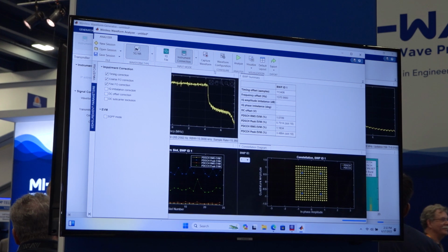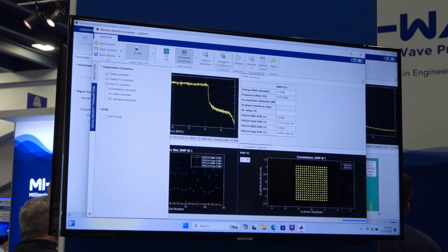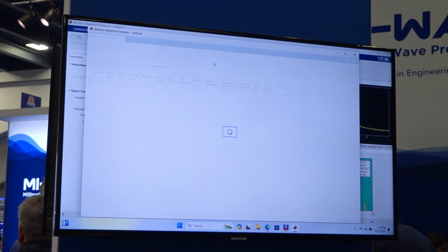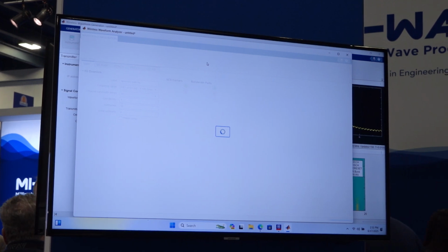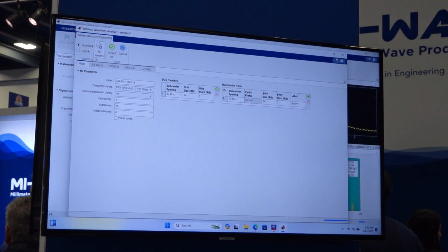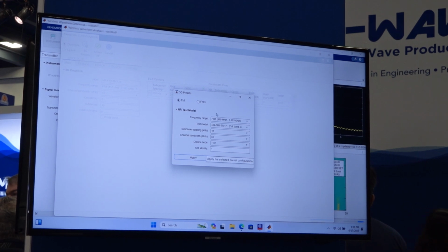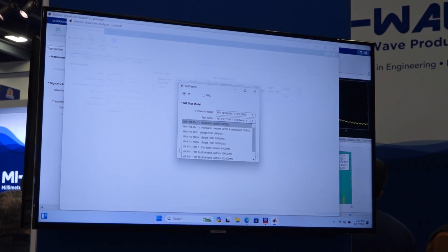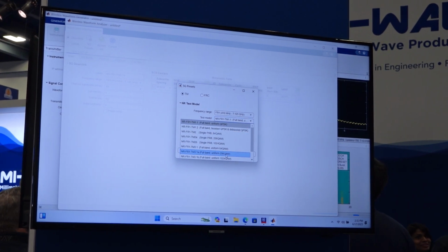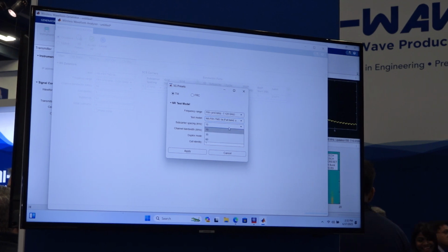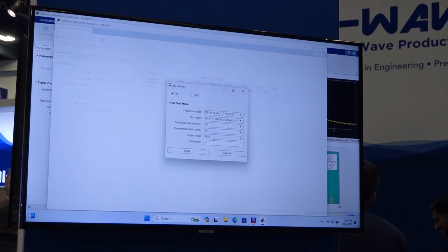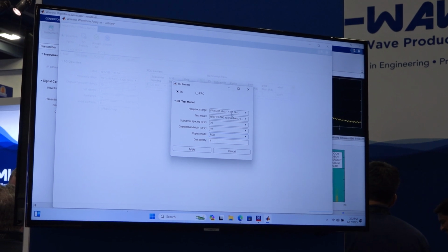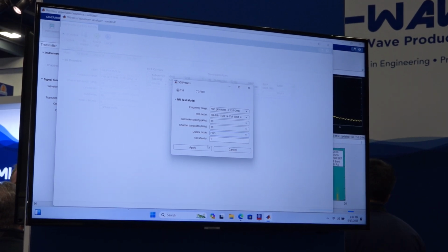Then before you capture the waveform, you can use this waveform configuration tab, which will bring up a window, and there are some presets for 5G. Since we're working in 5G, we want to make sure that we match the same 256 QAM signal here and set the subcarrier spacing and the bandwidth to be the same as we had on our previous generator.